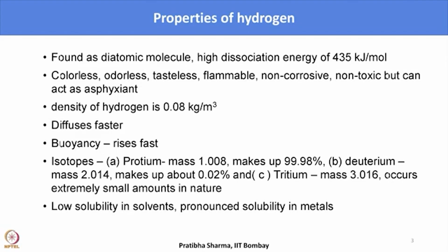If it is in confined spaces, hydrogen can displace oxygen, reducing the oxygen level and thereby cause breathlessness. If it reduces the oxygen level below a certain level, say 12% by volume, it can lead to severe health challenges, unconsciousness and others.